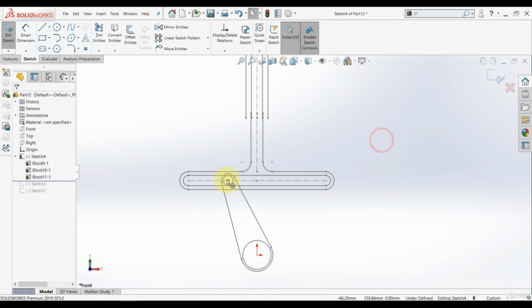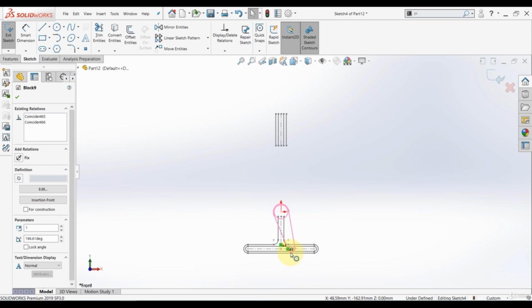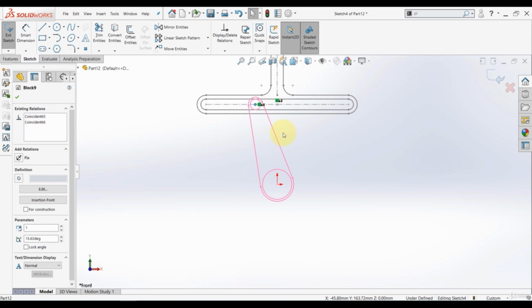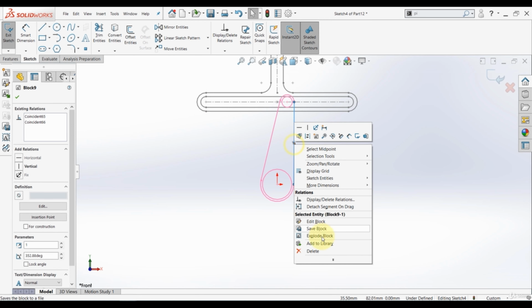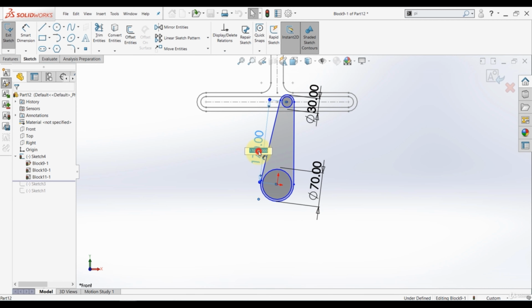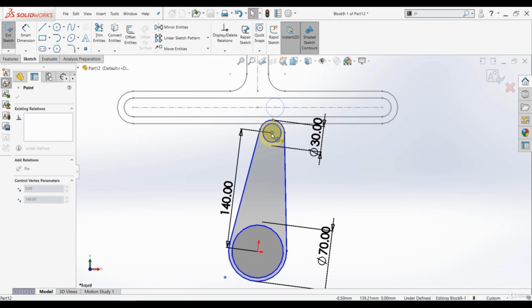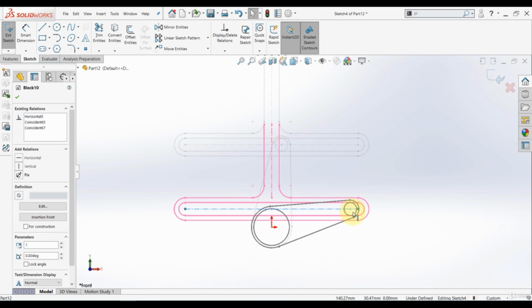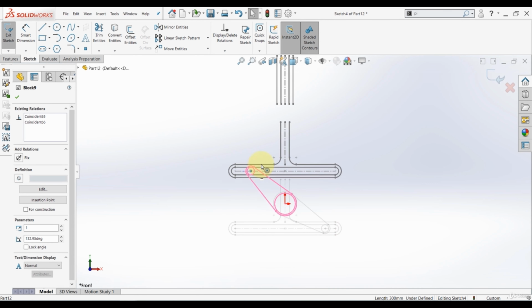And let's see the motion now. We still need to increase it a little bit, or simply we can reduce the length of this one. So now right click this block, and here instead of 170 let it be 140, and connect this circle to this one here. Then finish the block, and let's try the motion. Now it's correct.